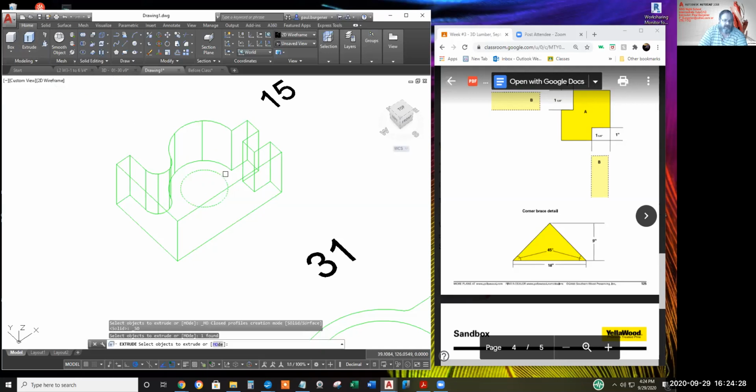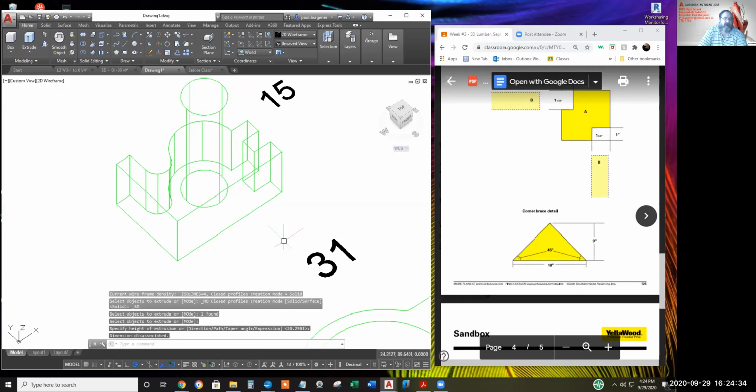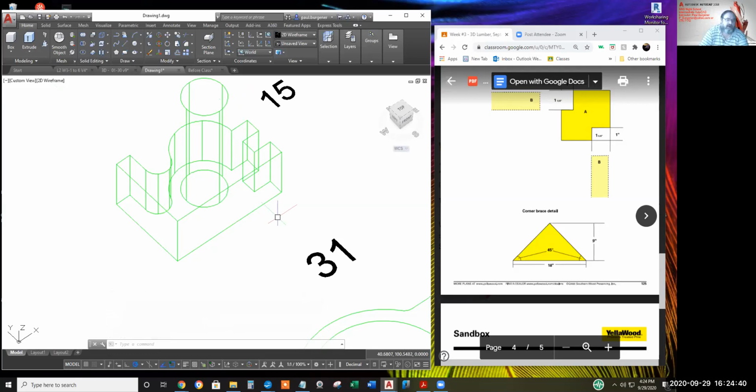The cylinder can be perfectly the same size as the plate you're trying to remove the cylinder from, leaving a hole. Years ago, if you made it the exact same size, there's some sort of glitch with the rounding off. And every once in a while, you'd have a kind of a skin across the top. AutoCAD wasn't quite sure which material you wanted on the top and bottom of the hole. But I think they've got that fixed now. Again, we can change it, spray paint it conceptual.